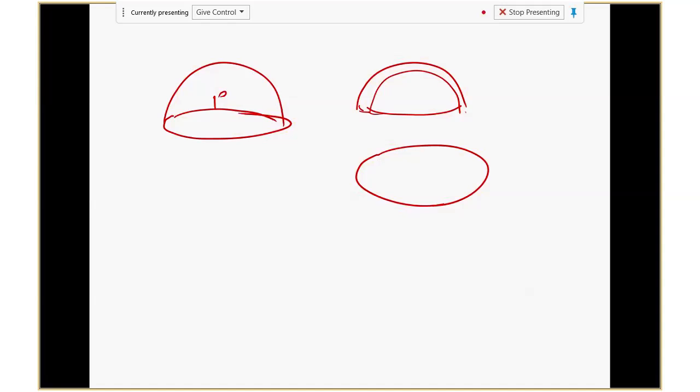On this cap, what kind of load do you have there? You should have pressure on all the area, everywhere, is that correct? Also, because it connects to the half sphere, along this edge you're going to have the tension between the plate and the sphere.